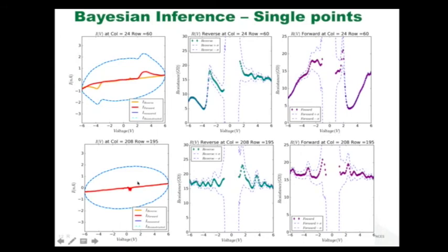If you look at the film, you can see that it's basically an ohmic-like behavior, and it's basically got a constant resistance to within error, and it doesn't change depending on whether you're forward or reverse. So the IV curves typically overlay each other in this case because we're not able to measure the ferroelectric switching. So what this method proves is that we can indeed use the Bayesian inference method to be able to infer what an IV curve actually looks like, even when we measure at much faster rates than is the norm.